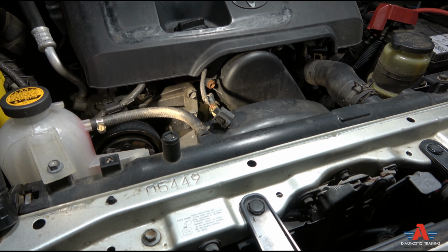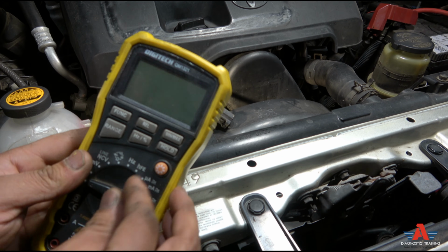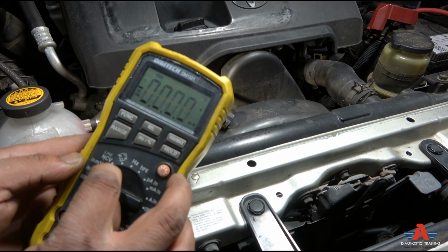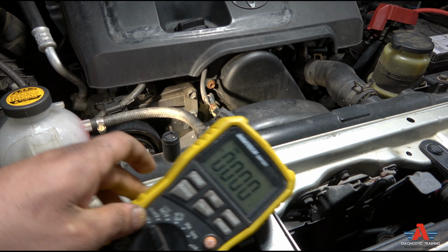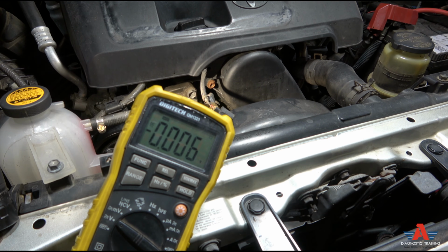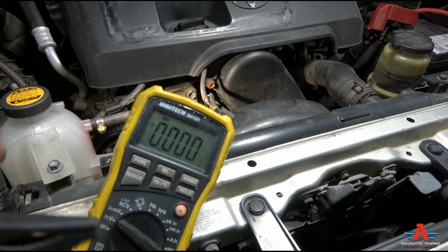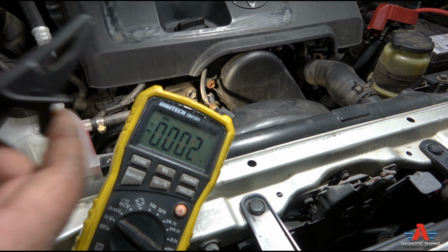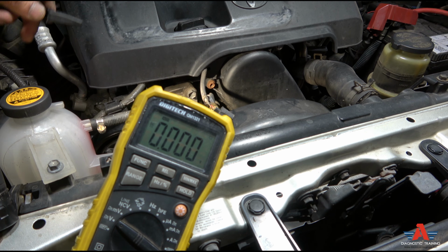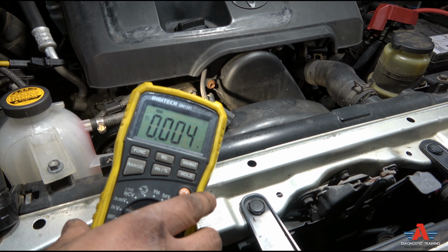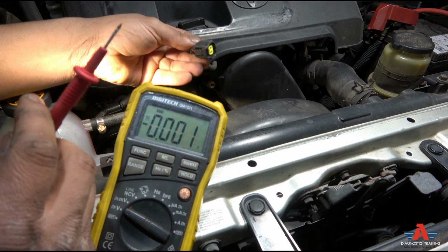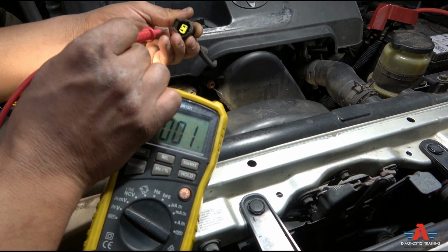All right, I'm going to grab my multimeter. Put the multimeter on volt setting, right? Because we're checking for voltage. We're going to look for that 5 volt. Obviously, the ignition key has to be on. So I'm going to put one lead to the battery negative. Okay, so I'll just find a body ground here, doesn't matter where. And the other lead of the multimeter, I'm going to go to that plug and I'm going to look for 5 volt.